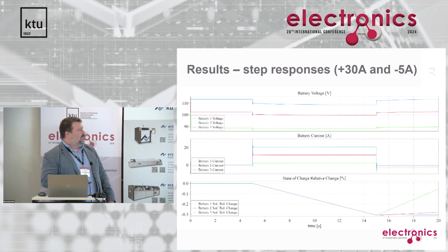So in those steps, you can see the battery voltage: of course, the best charged module has the most voltage drop because it has the highest current running out of it. And this lower module has a very low voltage drop because it has very low current.